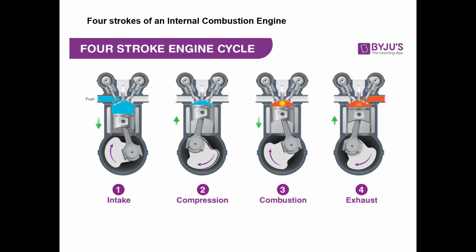Then let me talk about four stroke engines. There are 4 strokes, as I said. You have the intake stroke, the compression stroke, the combustion or power stroke, and then the exhaust stroke. In the intake stroke, the piston starts from the top dead center and when it goes down, your intake valve opens and the air fuel mixture comes into the cylinder.